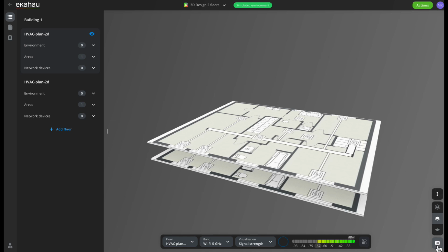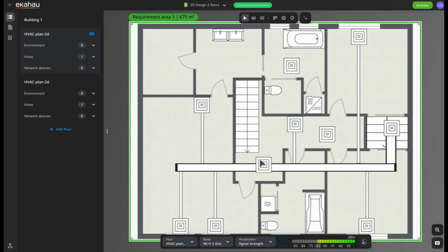Now, here we can see that we have some air ducts at our disposal that we need to modify and create a 3D element for, and then we have the stairs. Of course, we have the walls and whatnot. The height between the 2 floors is 2.5 meters or 250 centimeters. We have 10 stairs here. So we know the exact height, and we know the length. We know from here to here is about 3 meters. So we know we have 10 stairs, and so we also know the dimensions of these stairs.